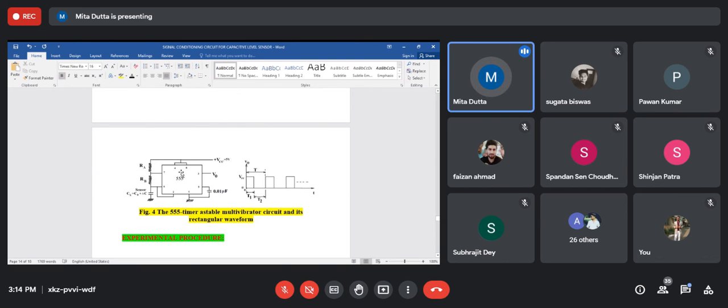And when the 555 timer chip is provided to us in the actual experiment, we have to use a Vero board, and there we are going to connect RA, RB and C like this, and to V0 we have to connect the CRO, and VCC with pins 4 and 8 shorted and connected to this plus 5 volt supply.